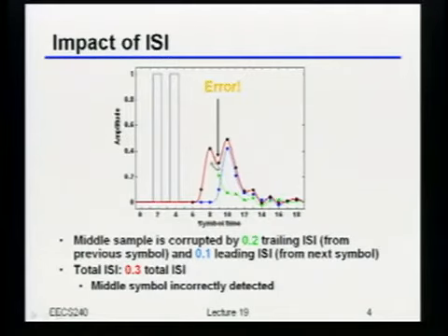Okay, Dan's shaking his head, but let's maybe get somebody else. Because it's a square pulse, the higher frequency components are getting there before the lower frequency. Ah, okay. So that's usually the physicist answer. There's dispersion. It's actually exactly correct, by the way. The high frequency components arrive first, and then the low frequency components arrive later.